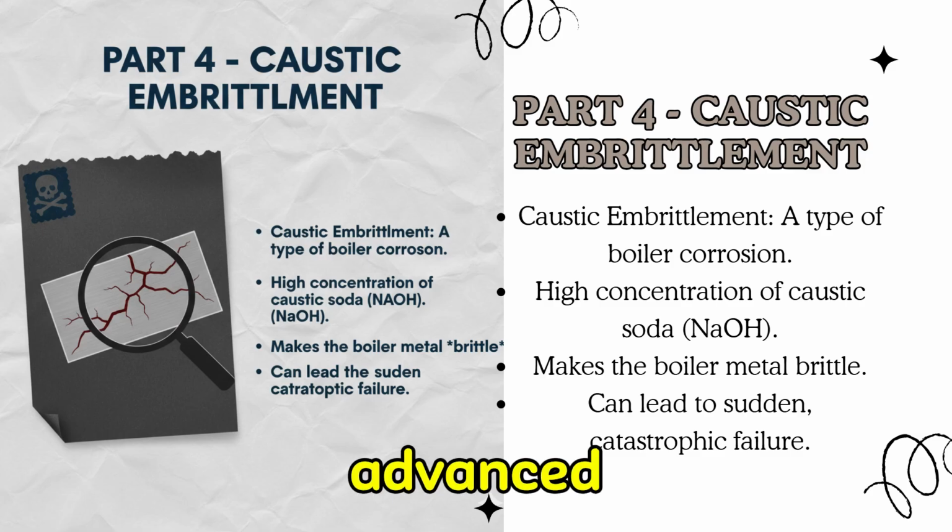Finally, there's one more dangerous effect, which happens under very specific conditions. This is a bit more advanced, but it's important to know. Caustic embrittlement is a type of boiler corrosion caused by a high concentration of sodium carbonate, caustic soda, in the boiler water, which makes the boiler metal brittle. Essentially, in high-pressure boilers, the water can seep into tiny cracks in the metal. The high temperature and presence of caustic soda creates a chemical reaction that makes the steel lose its strength and become brittle, which can cause it to crack and fail without warning.